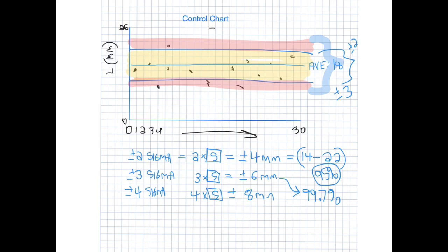And when you do, it just indicates if it's within range. And it can also indicate if you're starting to slip out of the range, and the operator can notice that. And usually that might be because there's tool wear or some problem with the lathe that needs to be fixed. But it gives you an advance indication that your process is out of control.